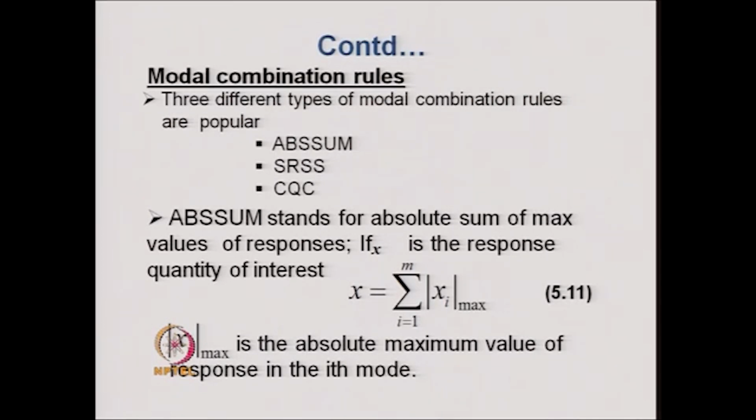The modal combination rules that we have are APSUM, SRSS and CQC. APSUM stands for absolute sum of maximum values of responses.